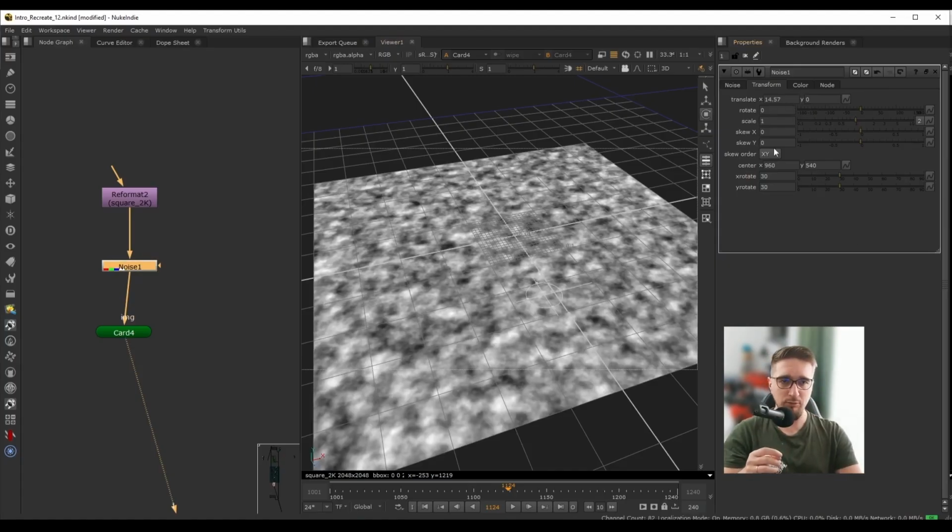So if I wanted to animate this translate X value, I can go to the beginning of the timeline. I can right click and set a keyframe. This will now show up on our timeline here. If I zoom in real close, we can see that there's this blue underscore kind of thing, and this indicates that we have set a keyframe.